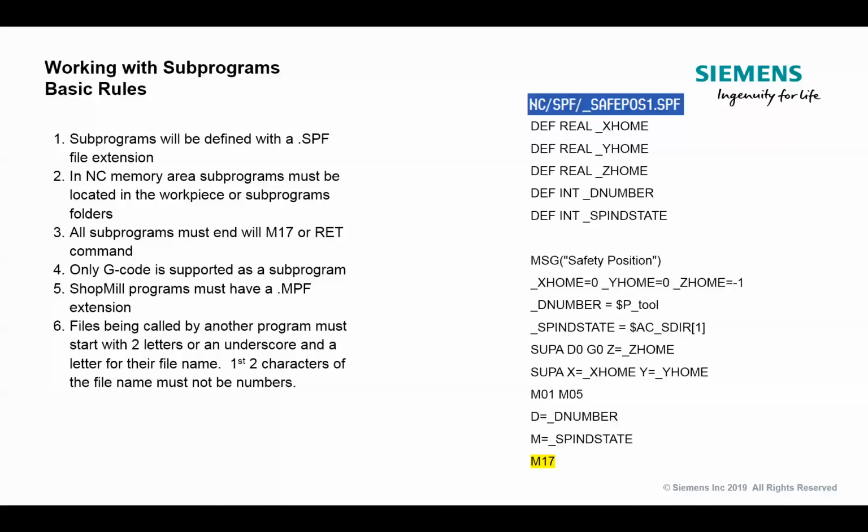So once you've created a part program and dropped it in that folder, when you write the program, you do have to tell it that the end of program is either an M17 or the RET command, which is a return command. Either of them work. You could interchange them, but you would want to switch if you were using an M30 or an M2 in that original source file. You'd want to switch it to an M17 or a RET command.